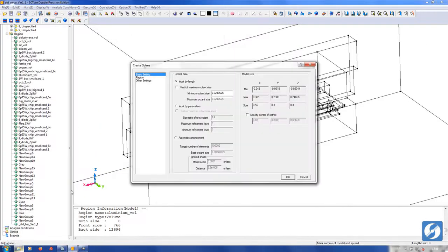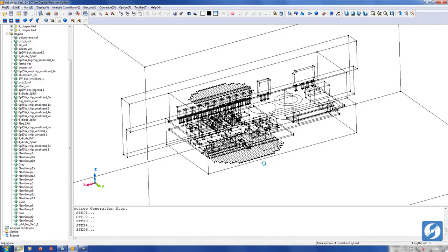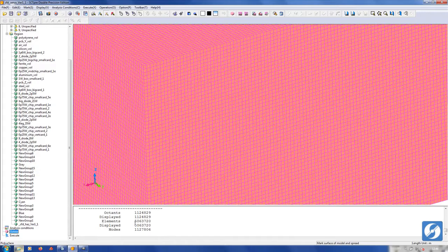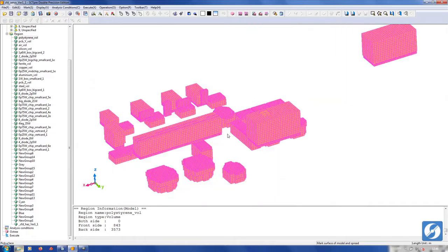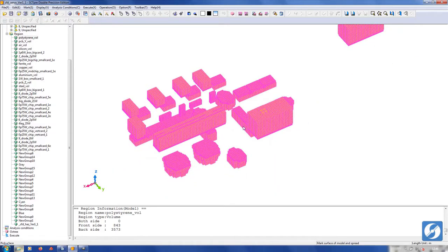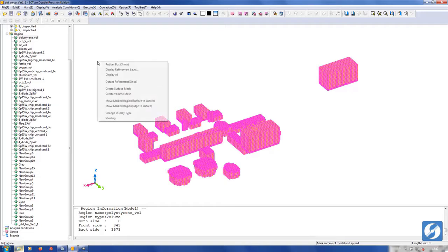As far as the mesh element sizes are concerned, I let the CFD tool build an automatic mesh of 5 million elements using the same settings as with the initial design. When it is done, I start to manually make the mesh of those parts uniform that will have wattage on. To do this, I use the volume groups the CFD code recognizes for each material. For example, this is how the mesh of everything made of polystyrene looks.